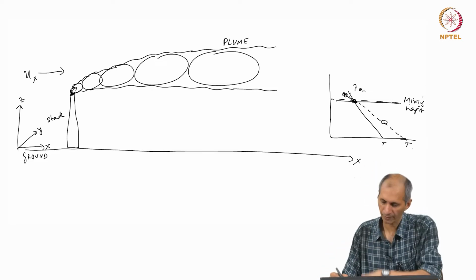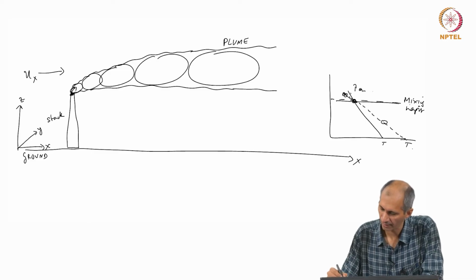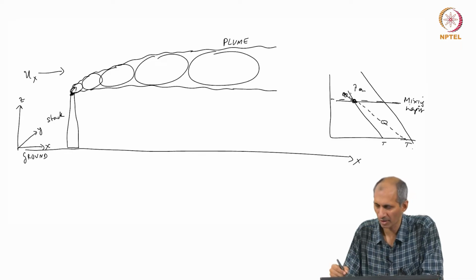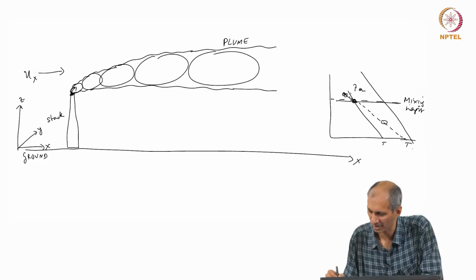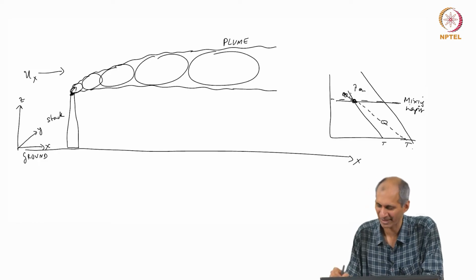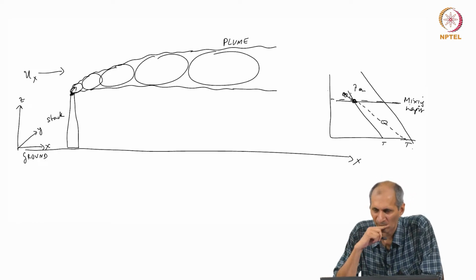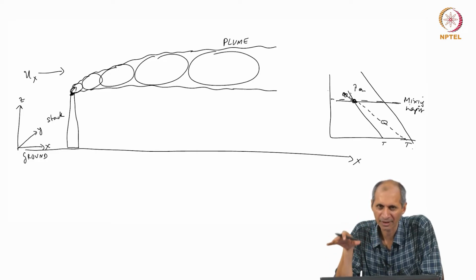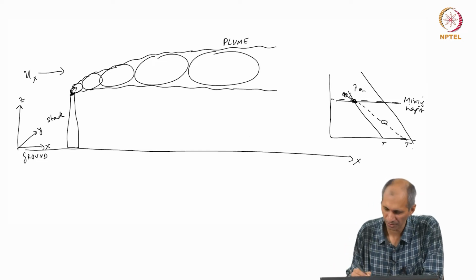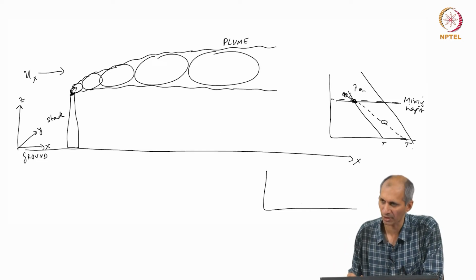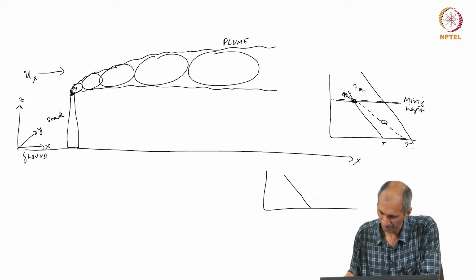There may be a case where you have the environmental lapse rate that looks like this, then this is always lower. Most of the times it is the other way around. So, we have a problem here. This can occur in some cases where the pollutant has no buoyancy at all, it will stay there, so the thermal effect is not really felt in this case. But normally, with pollutants like exhaust, which is most of the time higher temperature than the ambient, it is very likely that you will see this kind of behavior. A lot of times you will see this kind of behavior.